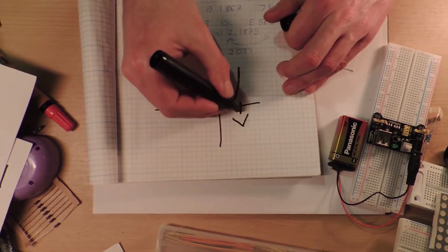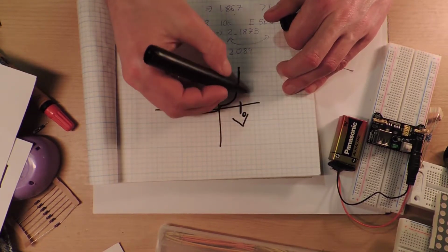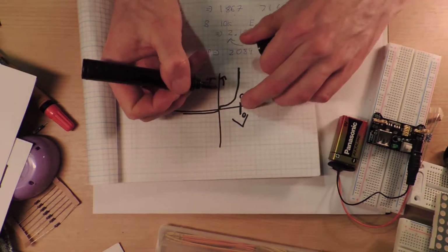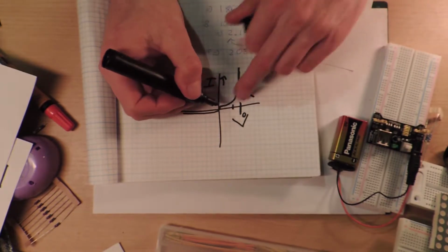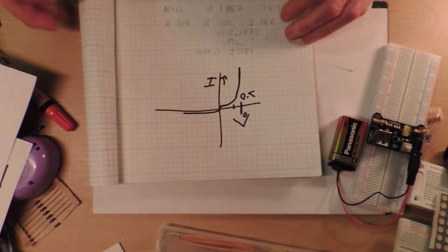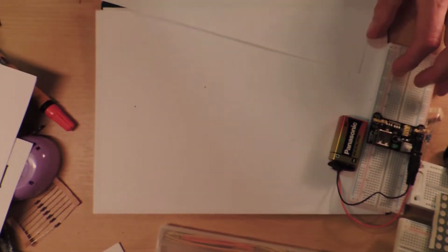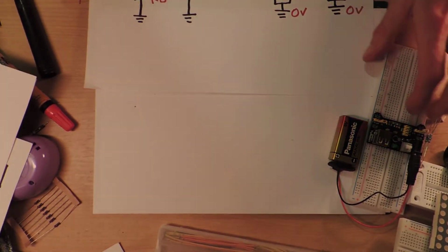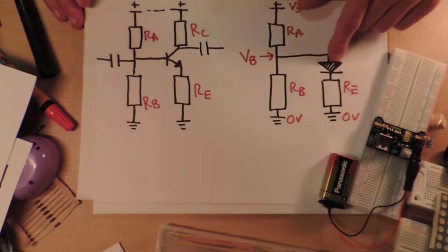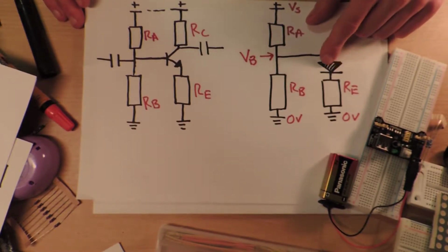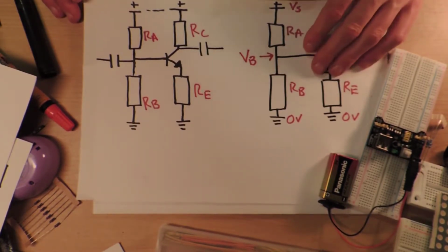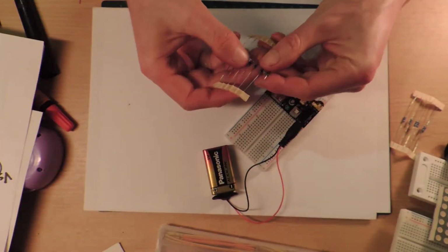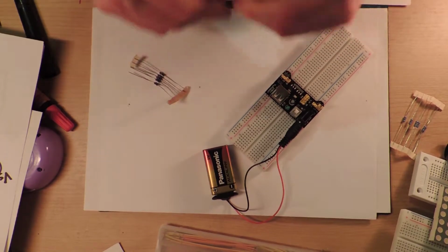So as we get to here, this is about 0.7 volts there. But according to the simulator, in all the circuits that I was testing, you're only getting a voltage drop of about 0.55 volts across this, because the current actually turns out to be so low. But anyway, these are 10Ks.